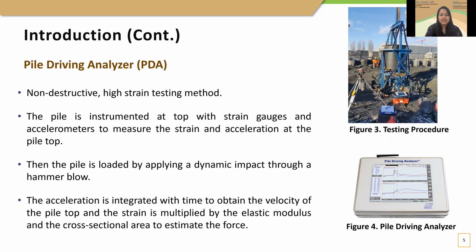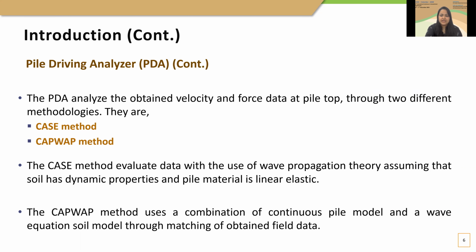The pile driving analyzer is a nondestructive high-strain testing method where a dynamic impact is applied to the pile top through a large hammer blow. So here the acceleration and the strain of the pile top is measured in order to identify the defects in the pile shaft. In pile driving analyzer, two approaches are used to analyze the obtained data, which are the case method and the CAPWAP method.